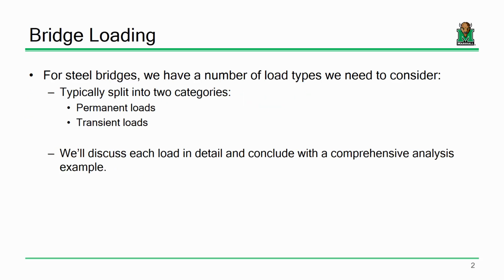So let's talk a little bit about bridge loading. And if you've got any experience with structural engineering, you probably think of things in dead load and live load. To be a little more specific, and I've mentioned this before, I like to talk about things in permanent and transient fashions. Permanent being loads that are always there, transient being loads that move. Okay? And we will spend a lot of time discussing the live loads on bridges, because it's not complicated, but I would say it's intricate.